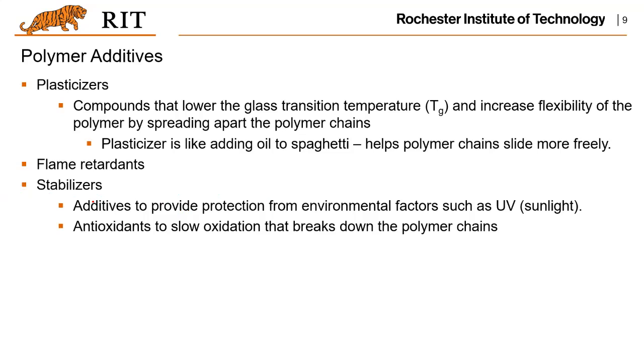Also, there are some materials added to prevent flames or stabilize the material, to prevent possible degradation from environmental factors such as UV or oxidation, and so on and so forth. These add-ons could change those temperatures: the glass transition temperature, the crystalline temperature, and also the melting temperature.